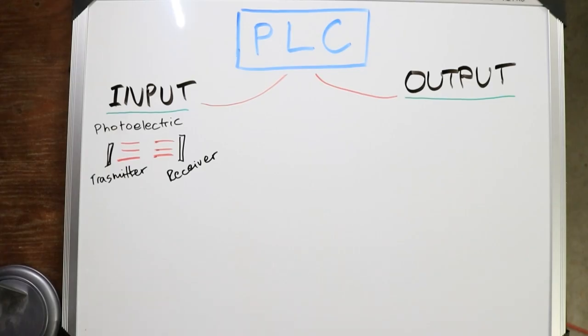A good example of this photoelectric sensor would be a garage door. It has a through beam that goes from one side to the other. When the garage door is coming down, for safety, if something walks past that through beam, it's going to cut off the electricity to the garage, and the garage door will not go down. It will stop the garage from continuing what it was going to do, to prevent any injuries to somebody that's walking under it. And usually a through beam or photoelectric sensor is used for safety in the warehouse, in the factory.